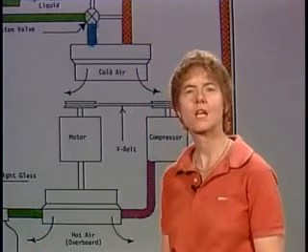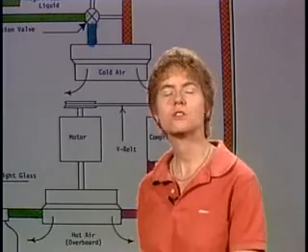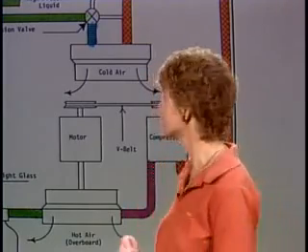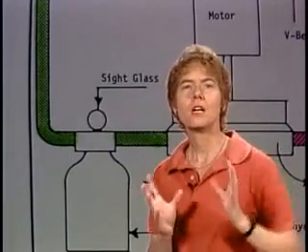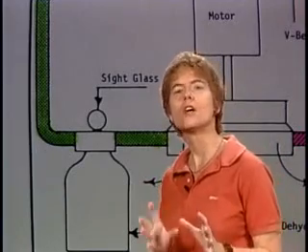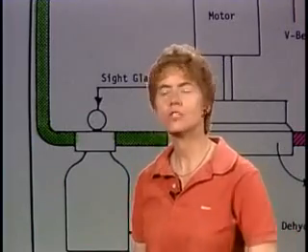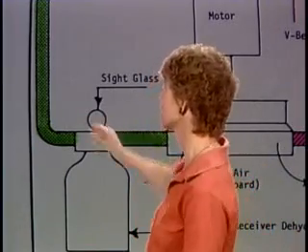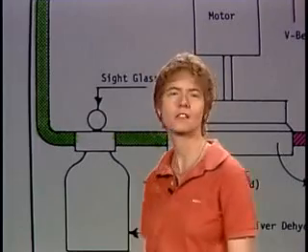Now, when you're servicing air conditioning, one of the things you take a look at is the sight gauge, which is just over a little bit to the left of the condenser there. If the liquid level sight gauge shows a low Freon charge, what you need to do is operate the system for a period of time to get a stable condition and then recheck the level. Before you start adding Freon or anything, let the system run for a while, 5 minutes or so, in order to stabilize and recheck that sight glass.